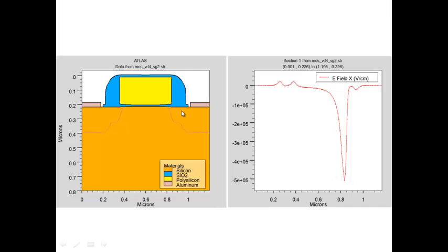And now as you enter into the drain, you get a lot of electrons, an N plus region. Remember, the drain is an N plus region here, so the electric field collapses here. The electric field goes back almost to a very small value. So the picture that you should have in mind is that there's a very high field region.